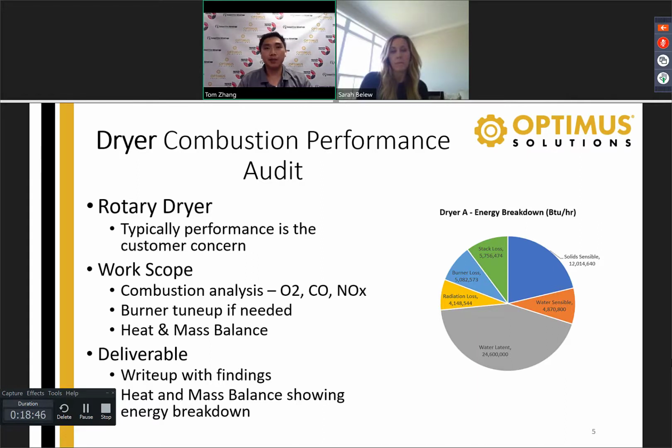We can then take that percentage of water, take the energy it takes to heat and evaporate that water, and show the dollars you would save on fuel if you reduce that water, and on the other side of it, the increase in the production rate that you have.